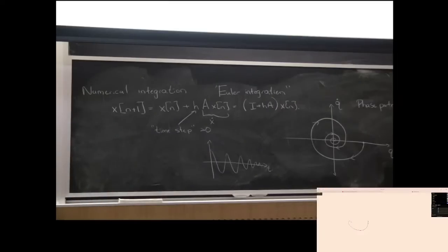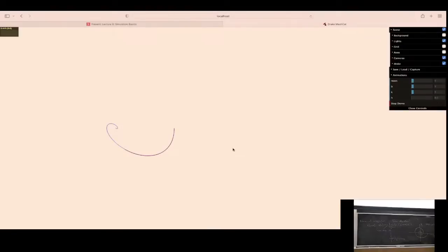We're seeing an initial condition here, and this is the origin, and I can change the stiffness and damping and the like. This is chosen with a pretty small h. h is chosen to be 0.1 seconds here. I have a mass of 1, a damping of 1, which I should have picked 0.1 or something, and a stiffness of 2. So these are all around the number 1, and I get this sort of reasonable solution.